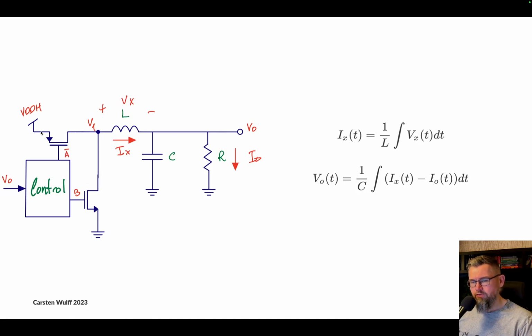But the principle is you charge the field in the inductor, which sort of sets up a current, or the current sets up a field, and the inductor stores that field such that when you turn off the PMOS and you turn on the NMOS, that current doesn't dissipate immediately. It continues to flow in the direction of the arrow. Now, it will continue to flow in that direction until the current becomes 0, and then it'll actually turn around.